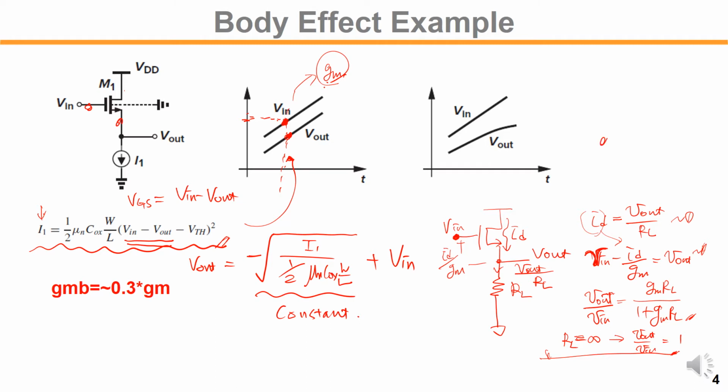The small signal gm is 2I over overdrive voltage, or two additional gm equations. So we can easily find the gm based on this equation. To find the actual value of gm, it is important to find the actual I1 and the actual overdrive voltage for the device M1.